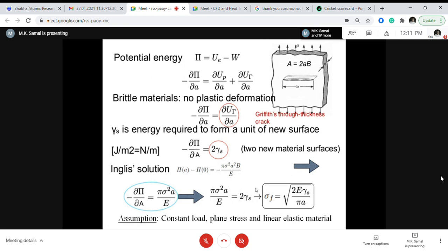It means the material is not fully brittle, not totally elastic; some plasticity is there. No matter what you do, you cannot avoid it because the material is ductile. However, we will try to extend the concept of linear fracture mechanics to this class of material where plastic deformation is unavoidable, but it will be very small. So if it is very small, how do we take care of the plastic deformation in the calculation of the stress intensity factor?